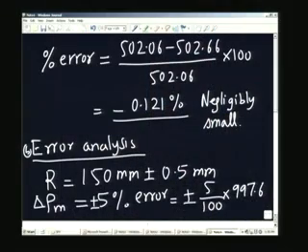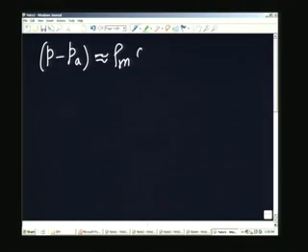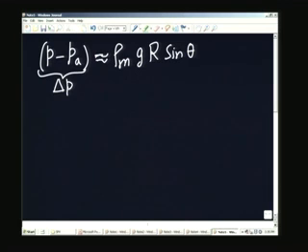So, the point is, we go back to the formula which gives delta p or p minus p a. I am going to make the approximation that the density of air itself is neglected. So, it becomes simply, approximately rho m g r, and in fact, I can also ignore the area ratio there. If you want, you can take into account plus a r. This is approximately this one, and I will just call this delta p, as a symbol representing P minus Pa, or the gauge pressure, delta P.